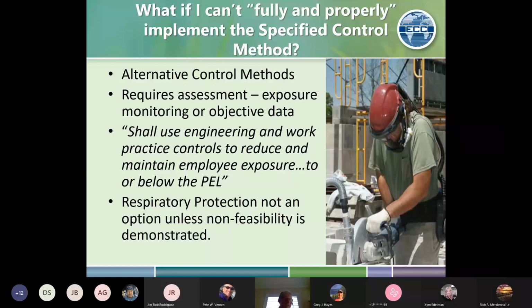So it might not meet the definition of respirable dust anymore. Usually if you sample at too high a flow rate, it's going to take out even smaller particles, so you're biasing your sample low. If you sample at too low a flow rate, it's going to allow some of the larger particles to pass the cyclone and get up on the filter, so you're going to bias your results high. So keep that in mind. Whichever cyclone you're using, check their specs and make sure you set the flow rate of your pump to what they tell you in order for it to work properly.